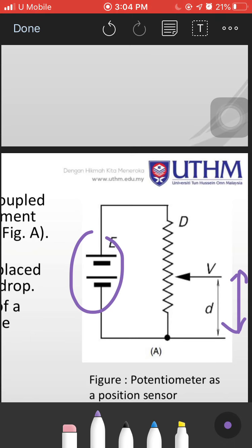For example, in this configuration, if you apply 10 volts across the resistive element of the potentiometer, the maximum output voltage will be equal to the supply voltage at 10 volts. This means the full scale length is equal to 10 volts. Then the potentiometer wiper will vary the output signal from 0 to 10 volts.